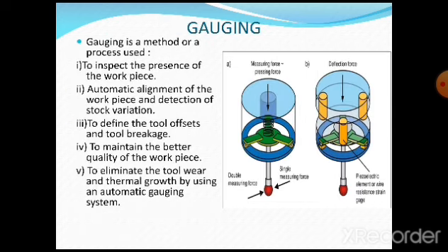So now we need to understand one more important concept here. Whenever you are going to carry out the manual operation, first of all, you are going to take all the dimensions of the given raw material. Then you are going to fix the workpiece on a headstock chuck if you take a simple lathe machine. Okay, then you are going to start your operation. Then again you are going to take it out for the measurement. One particular operation is being carried out. So this is a manual continuous process, but such a process is not available in case of a CNC machine.